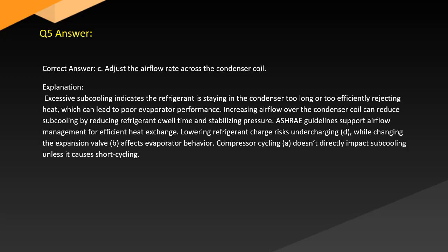Lowering refrigerant charge, D, risks undercharging. While changing the expansion valve, B, affects evaporator behavior. Compressor cycling, A, doesn't directly impact subcooling unless it causes short cycling.